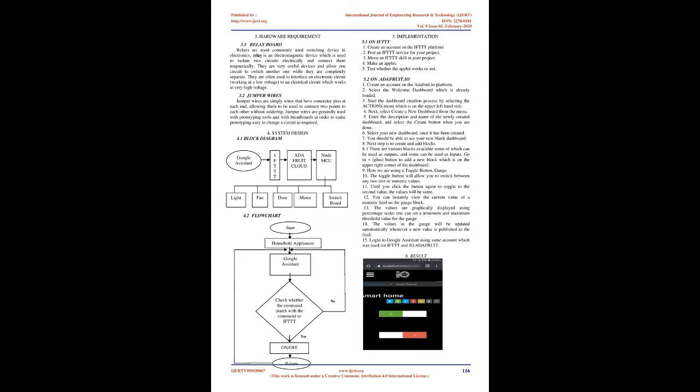There will be a specific auth token and username for our project. We have to include those auth token and username in the Adafruit coding template. In our project we have used 3 feeds for 3 relays. Each of them can be monitored in the Adafruit dashboard.